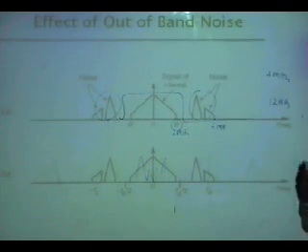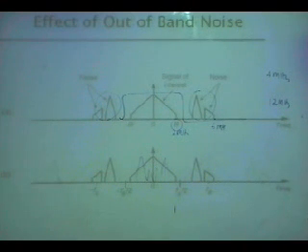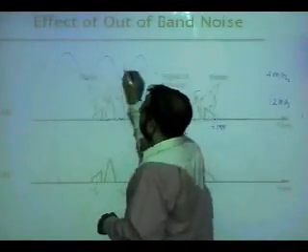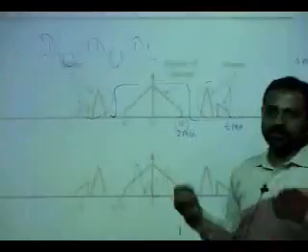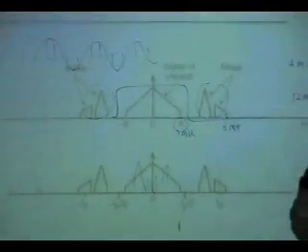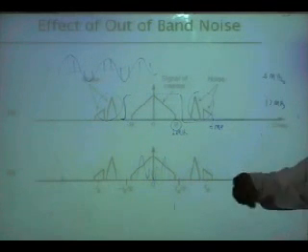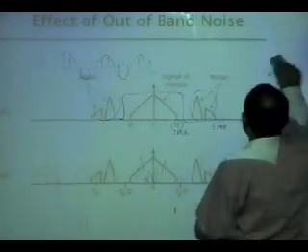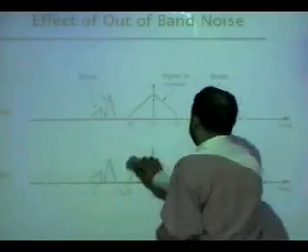There is something which is not yours, you bring it in, you throw it away, and then you say, now I also throw away samples, because my highest frequency sinusoid has more samples than what is required. Even 2 are more than enough. Even if I have 2, I can perfectly reconstruct this sinusoid. So that is the game. You say, I know I can perfectly reconstruct the sinusoid, so why waste samples?